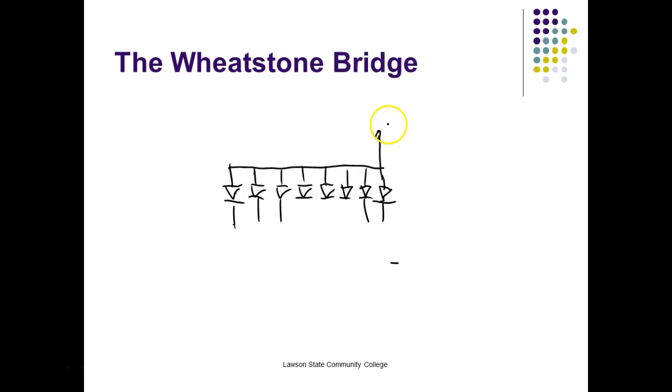You see some people put 1 resistor right there. But the problem with 1 resistor is you save money, but the more LEDs you turn on, the dimmer they get, right? So the standard way to do it is to put a resistor in each one of the cathodes. And here we would turn them on by somehow grounding that, right? You understand?